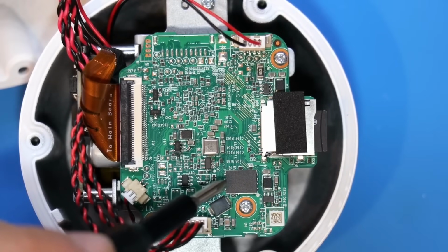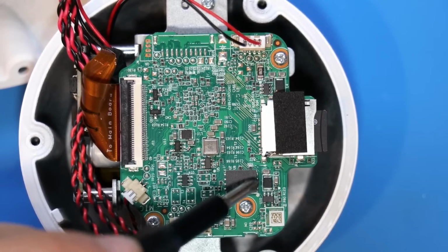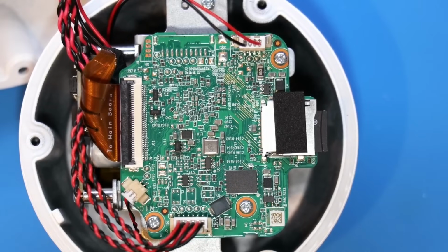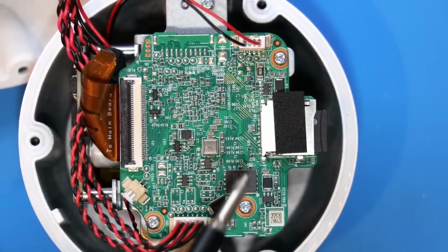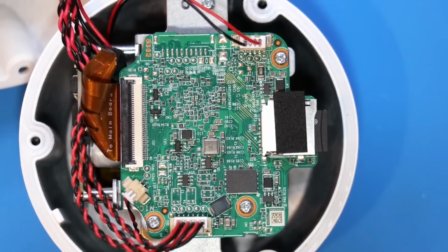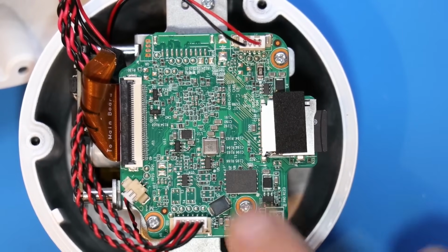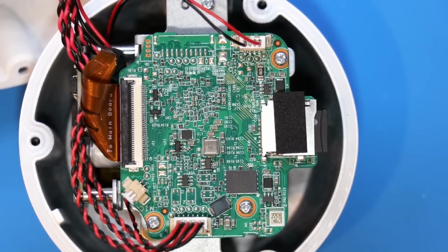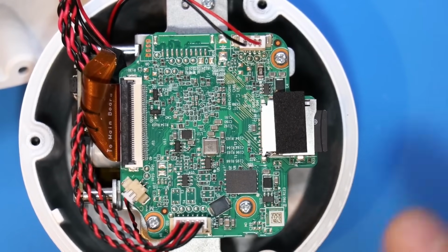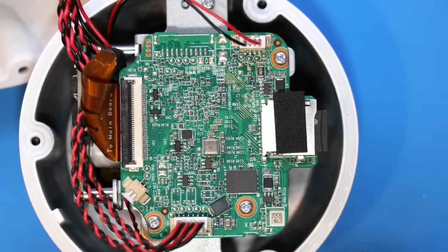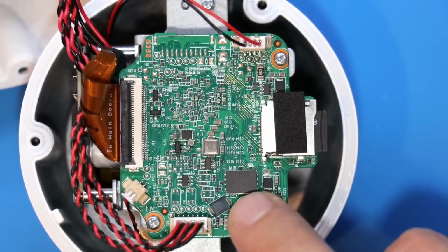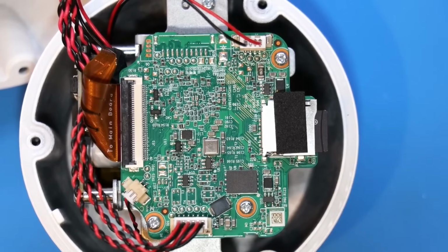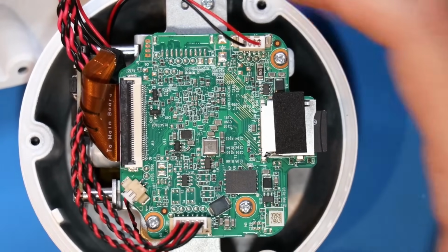You can see there are four pads on this side, four pads on this side. So this is a standard 8-pin. This does happen to be a NAND flash chip, and if I wanted to get at the firmware of this device and I did not have any other way to get access to it, a little foreshadowing there, I would be able to desolder this chip off the board and gain access to the device's firmware.